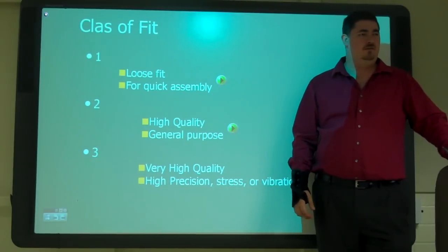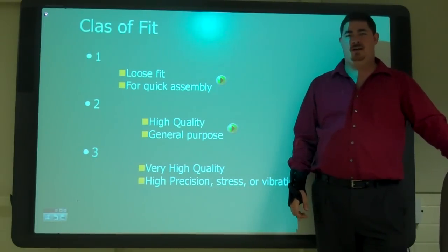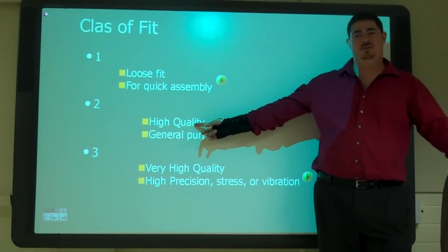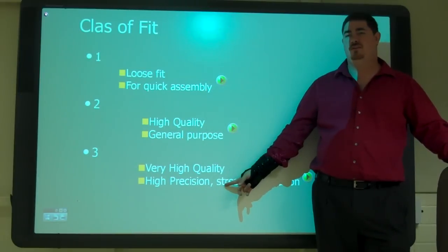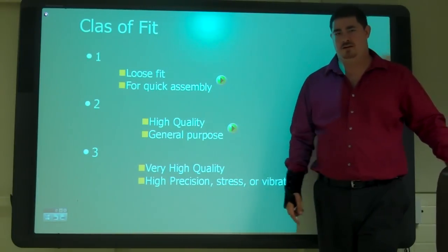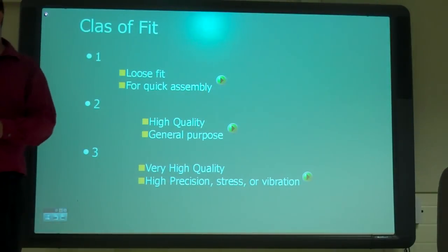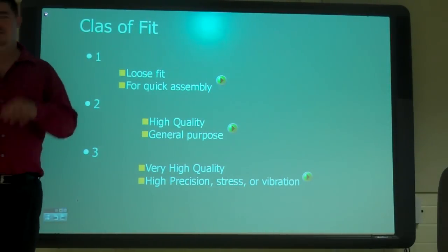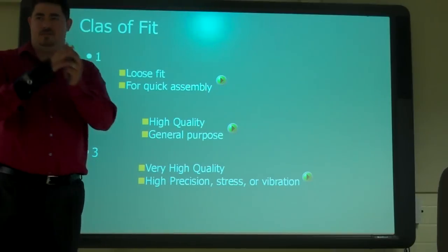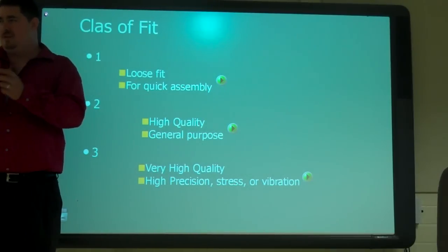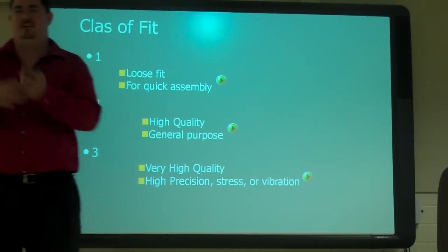So things like Loctite, what that does is it turns a class 2 into a class 3. So if you use the temporary Loctite, it'll turn the 2 into a 3, because it takes up that extra space. And that has to do with what the tooth form is and how the spacing on it was and everything.